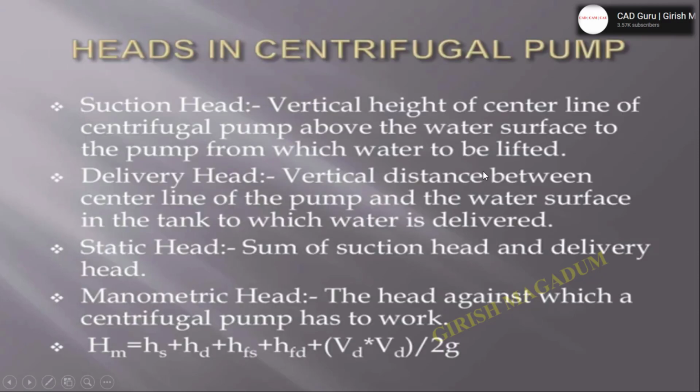The heads in the centrifugal pump: there are different types of heads. One is the suction head, the delivery head, the static head, and the manometric head. What exactly is this static head? We are mainly going to deal with it as the sum of the suction head and the delivery head, that is the output head, we can say.